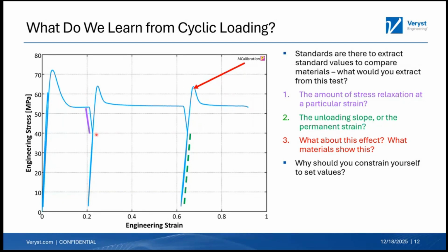So in this one test, I get information about the modulus, the yield stress, the shape of the curve. But then I say, okay, at 20% strain and 30 or 60 seconds, I'm getting about 20% stress relaxation. So that can be very valuable to me. Even if I don't explicitly model that, I might be able to say, okay, I've got this part loaded.